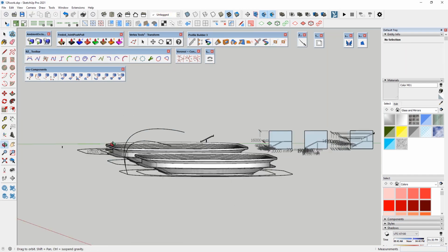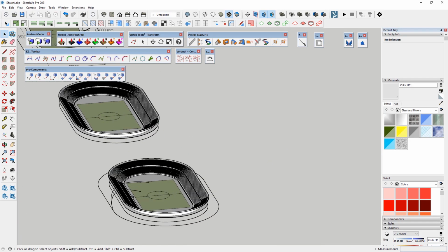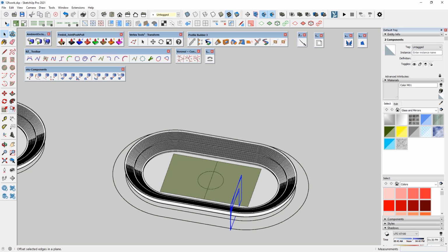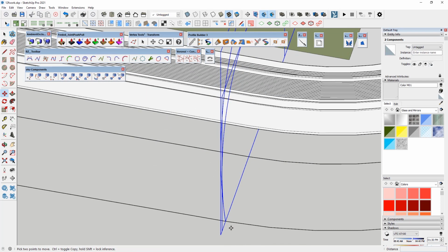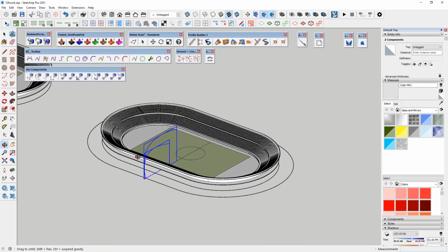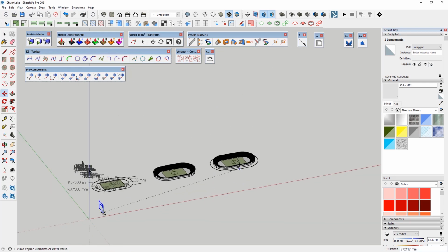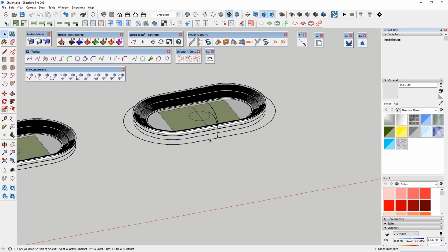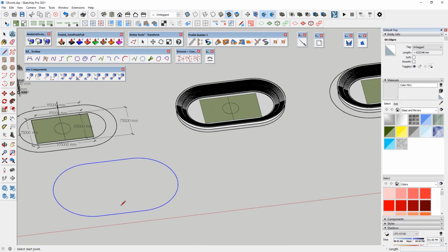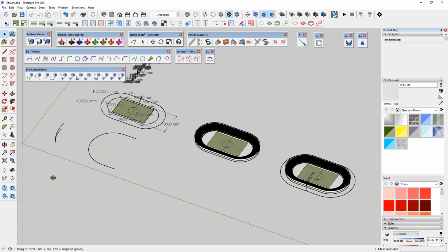Then we can convert both lines into components, and of course we need to move them to the center of the line, because all the time we will use only half of the line. The second half will be created by mirroring. So I will move the reference line here. And maybe we'll also move it to this place, because we'll draw everything from the 0 axis. Of course we also need the reference line for the follow me. And what is the most important, as I mentioned, we will only use the half. The opposite we can easily remove, also the surface and the edge from the inside.